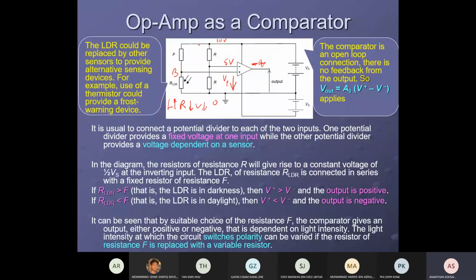Okay. So this is a street light circuit. When the light intensity is very high, on a sunny day, early morning at 7 o'clock, there is an LDR in the street light. The LDR sensor, when the light intensity increases, the resistance of the LDR will go down. The voltage across LDR will go down. So the B input positive will start to drop. V positive will start to drop compared to the V negative. Output immediately turns negative. The light bulb will be shut down. This is the automatic switch. This is the circuit used for street light.